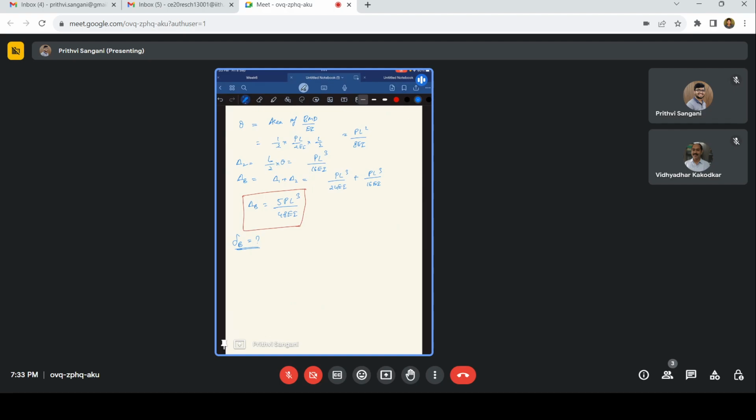Again, basically what we are trying to do is apply the force, find out the displacements, and get the compatibility conditions there. We can't always say that the delta in the determinate structure and the delta with the redundant forces are zero. So far we also discussed the support settlements, right? That has to be included in the compatibility equation to find out the support reactions in the members.